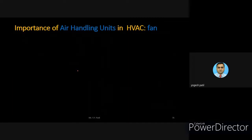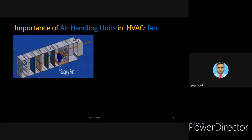The next very important part is the fan. Yes, this is the supply fan. This fan catches the air from the atmosphere and provides it to the remaining sections of the building. It pulls the air in from the outside, through the dampers, then through the filters, then the coils, and then this fan pushes it out to the ductwork, because after this there is ductwork. You can see this section is connected to ductwork, so it will push the air around the whole building.